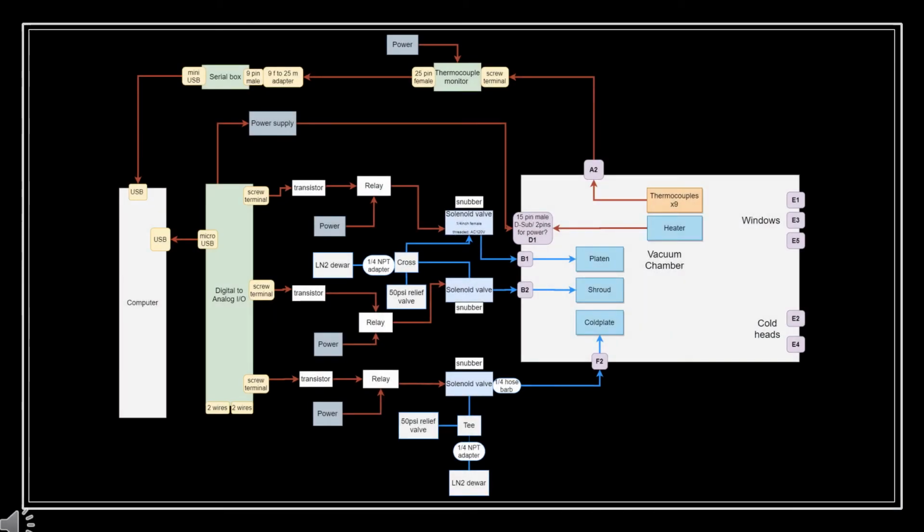The thermal control of our system has also been improved. Previously, issues arose in our experiments when the CO2 atmosphere would be significantly warmer than the cooled surface that the ice was depositing onto. This formed a very dramatic thermal gradient, causing internal stress and fracturing in the ice sheets. In order to alleviate this, the new chamber has a platinum shroud cooling system, allowing for the atmosphere of the chamber to be cooled individually from the deposition plate.